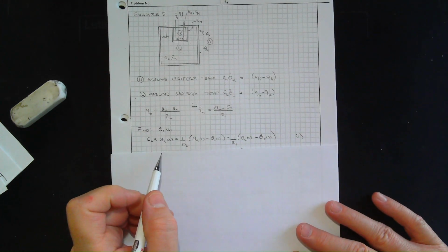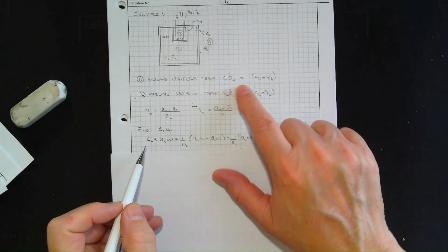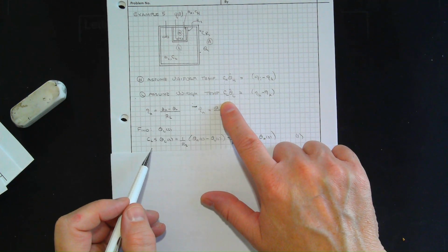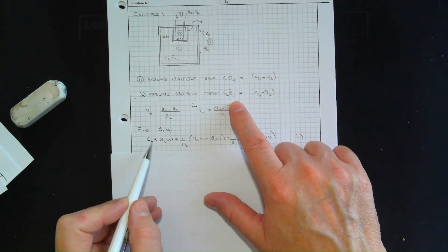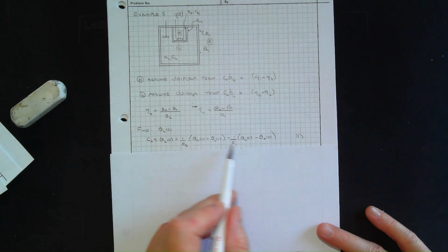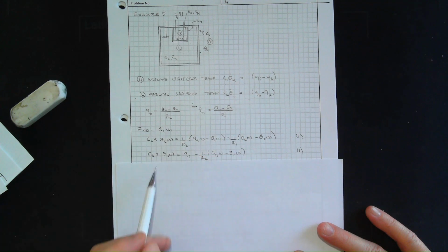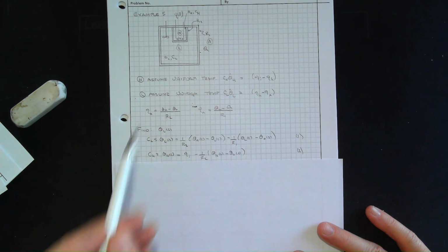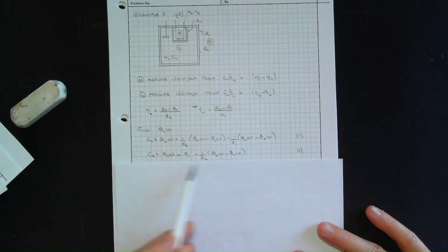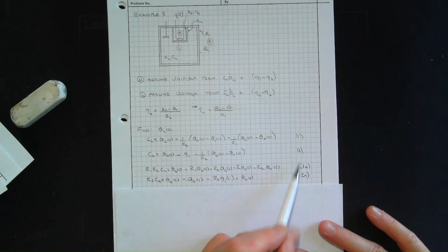So we can convert to Laplace. If we want to make a transfer function, then if we look at the low temperature side, that'll become CL S theta L of S. Okay, and just converting everything into Laplace, put the little s's on it. Then we can substitute our stuff into here, that this one, CH S theta H of S, right here. And so now the algebra begins. Step 1, clear the denominator. That's what takes 1 to 1a. And I do the same thing here with 2 to 2a.